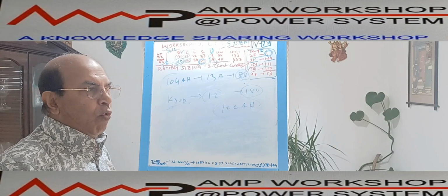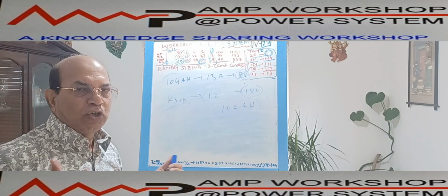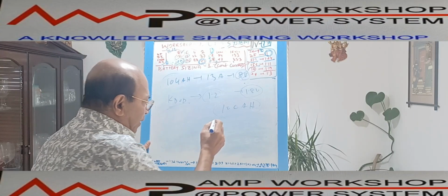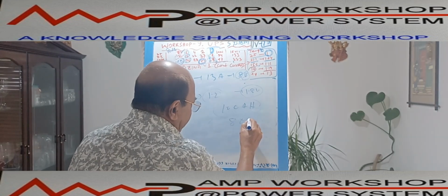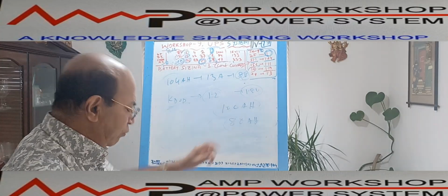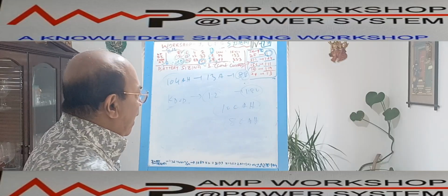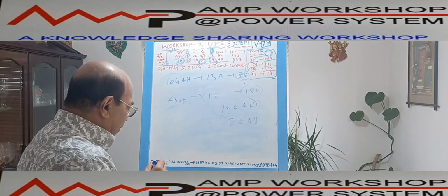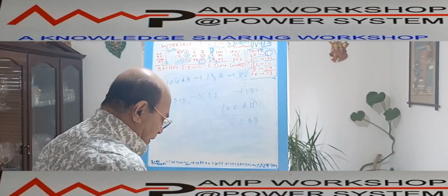Most manufacturers recommend that when the battery capacity drops down to 80%, for 100 ampere hour, after testing, if we see the capacity has dropped down to 80 ampere hour, then the manufacturer recommends don't use this battery, discard it and replace it with a new battery. That means it has already reduced by 20%, 20 ampere hour, from the original capacity over time.